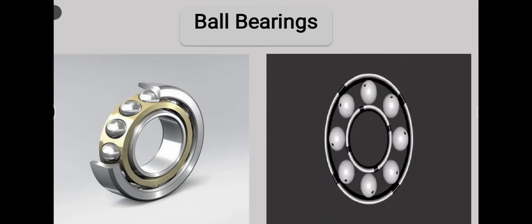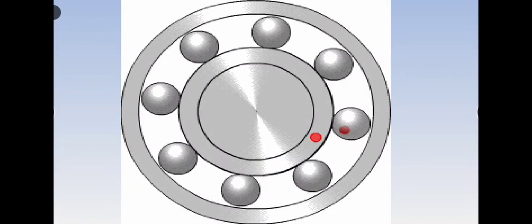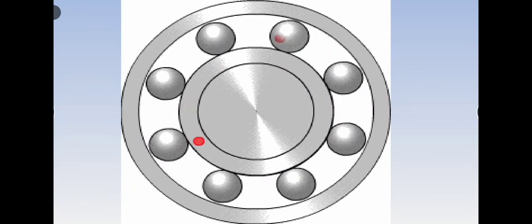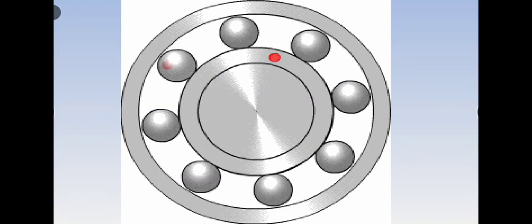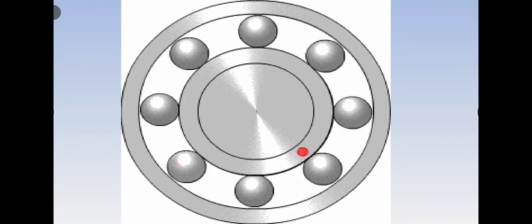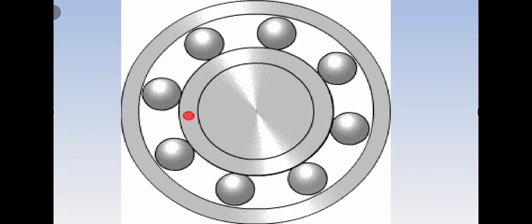Ball bearings provide very low friction during rolling but have limited load carrying capacity. This is because of the small area of contact between the balls and the races. They can support axial loads in two directions besides radial loads. Ball bearings are used for controlling oscillatory and rotational motion. For example, in electrical motors where the shaft is free to rotate but the motor housing is not, ball bearings are used to connect the shaft to the motor housing.